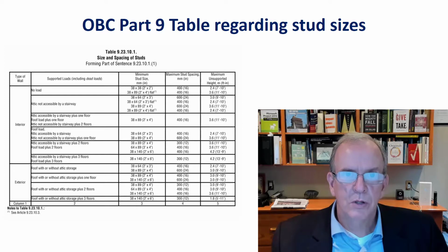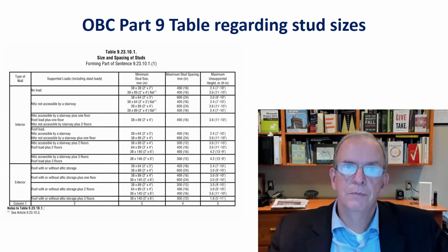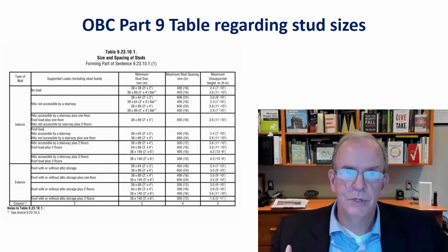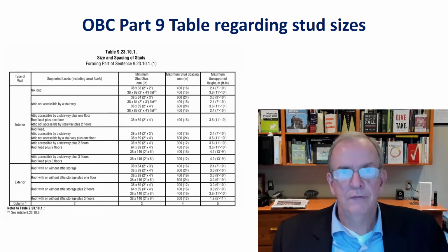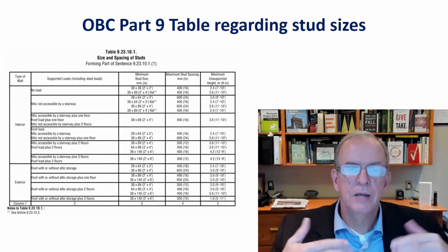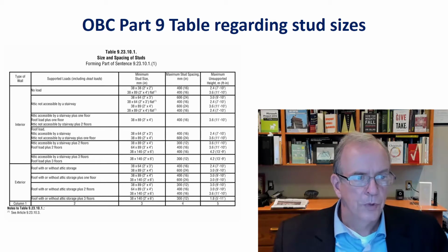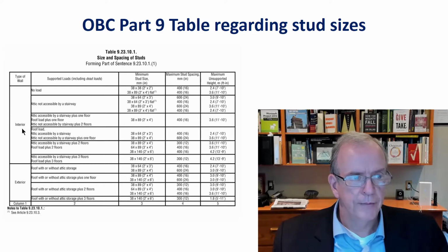The exterior wall is typically going to be carrying more load because the snow load is transferring through the outside walls, especially if the house has roof trusses, because the interior walls are typically non-load bearing in a trussed roof. And we'll talk about that in the next lecture, or Chapter 9 of the book if you read ahead.